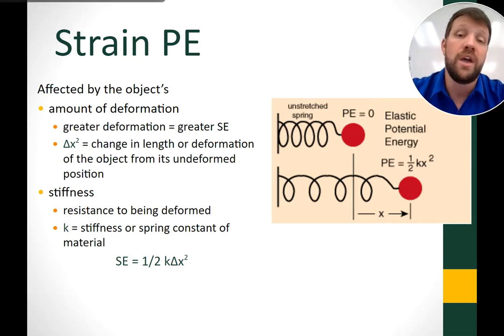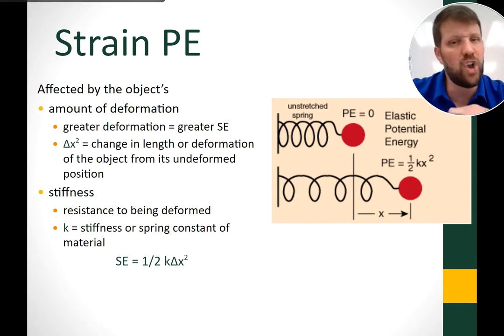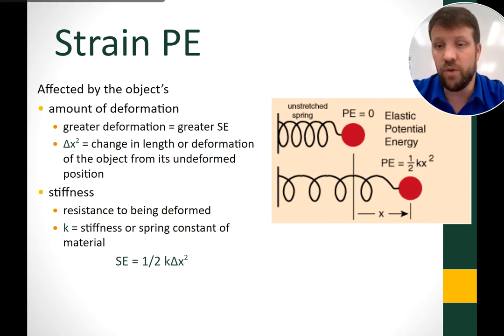And if you remember, the force applied by a spring is the spring constant, k, times x, its displacement, its overall stretch, right? Now, the amount of deformation is going to be a very similar type thing here, okay? So a greater deformation is going to have a greater strain energy overall, and this is going to be based on that delta x, how far something is stretched. And what this is to say is, if we have our rest position and we pull this out here, we apply a force to pull out the spring and hold it right here.